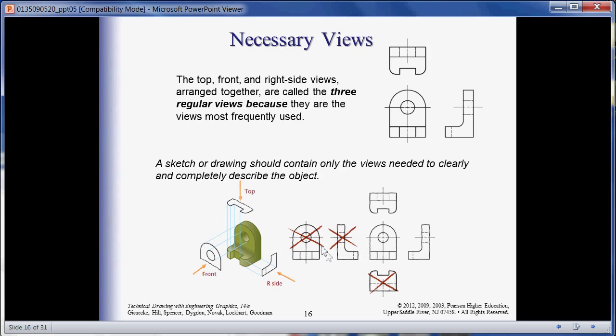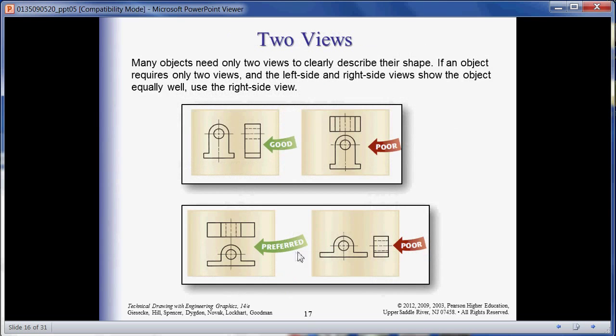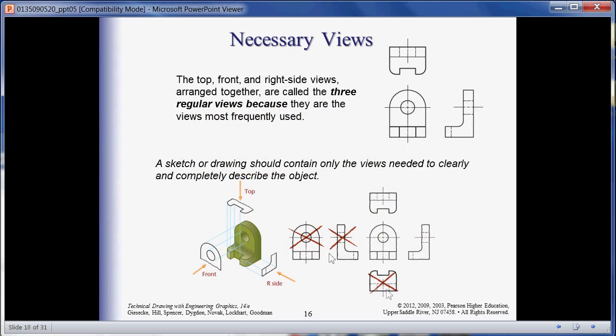It's a mirrored image. And then the back is basically the same as the front. Actually, the author made a mistake here. Let's see. These lines, oops, let me go back. These lines here should all be phantom, since if you look at the back, all this detail is hidden if you're looking from the back. So there's an error right there.